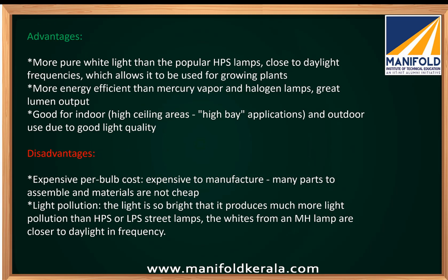Advantages: more pure white light than popular high pressure sodium lamps, close to daylight frequency, which allows use for growing plants. So even we can grow plants under metal halides. More energy efficient than mercury vapor and halogen lamps, great lumens output, good for indoor and outdoor use due to good light quality.